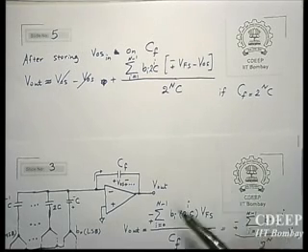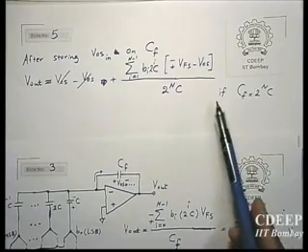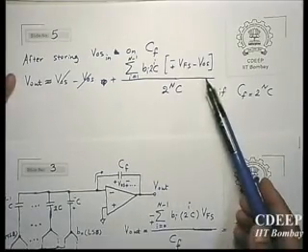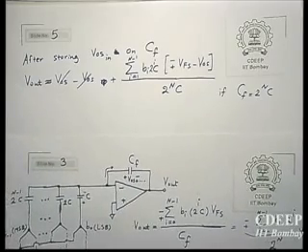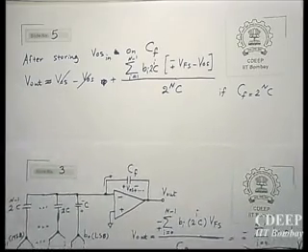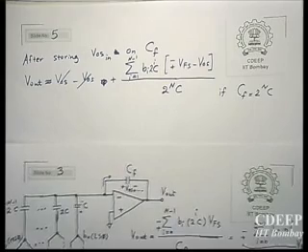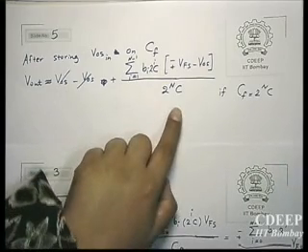So what remains is only gain error, and that gain error again will be easily compensated afterwards. So we don't compensate gain error here. It can be compensated at a digital level, I mean by the software,